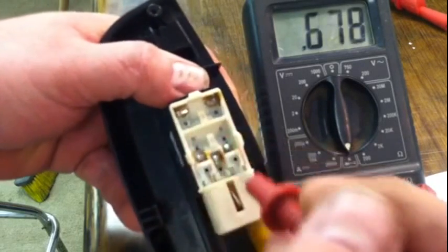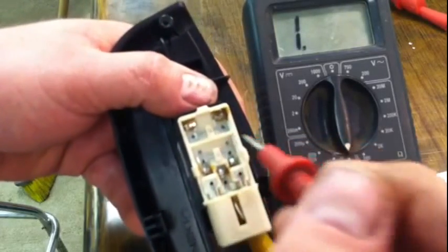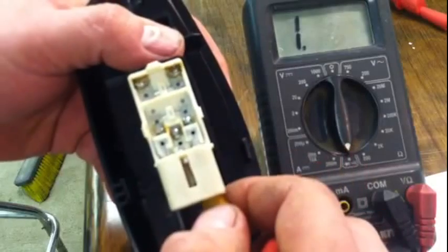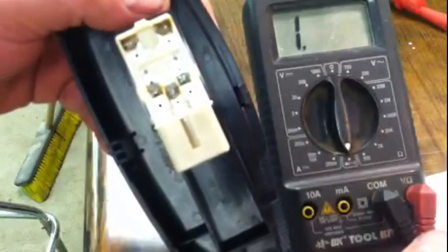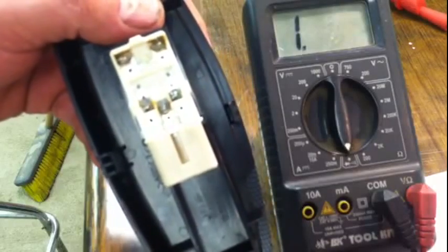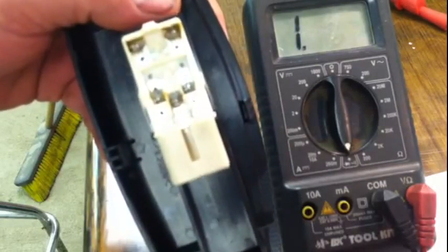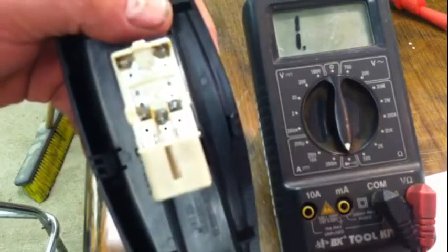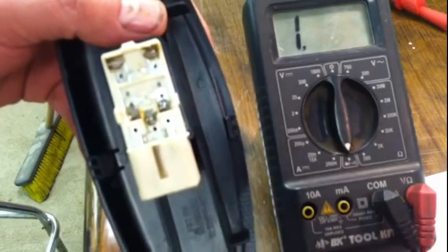And what that does is impede the amount of current that can flow through this switch. But you can't roll the switch out just for that. And like I said, this is a Chevy Aveo. They're not a real popular car anymore, and a lot of parts stores don't carry parts for them. For this switch, I have to get it from Virginia. I've already ordered it, but you want to make sure you go through every single bit of testing you can to make sure this is bad.